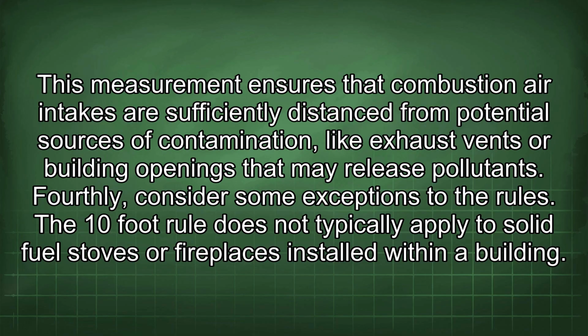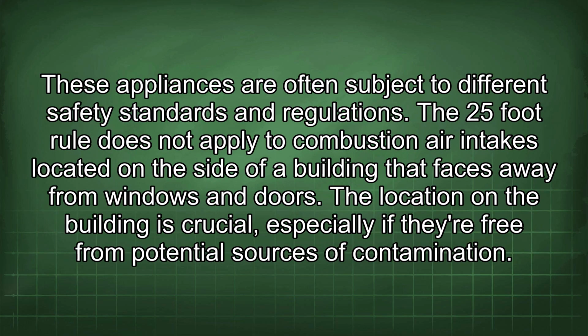Fourthly, consider some exceptions to the rules. The 10-foot rule does not typically apply to solid fuel stoves or fireplaces installed within a building. These appliances are often subject to different safety standards and regulations.